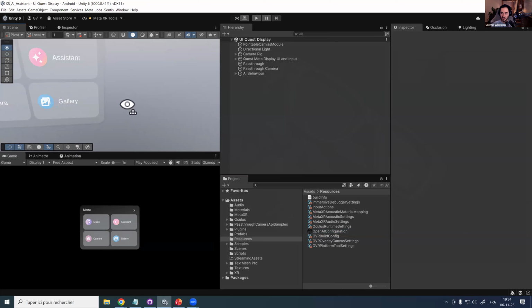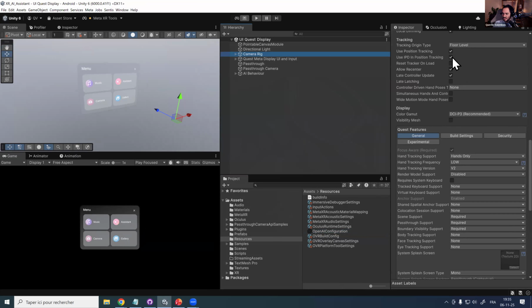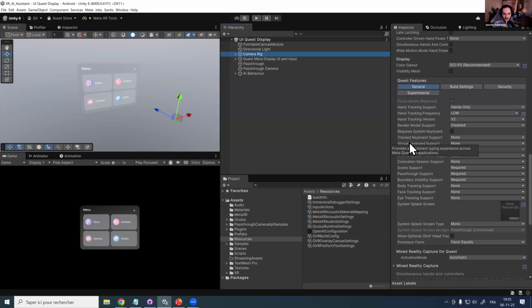The first thing I want to share with you is that here I'm using the Meta SDK. You have probably played with it. It is an awesome SDK that contains so many features that make our job so easy when creating samples, pre-configured scenes, or even interactions. For those who already know this SDK, there is something important to do if you are doing this kind of head-mounted mixed reality thing like I did, and that is to disable the Guardian.